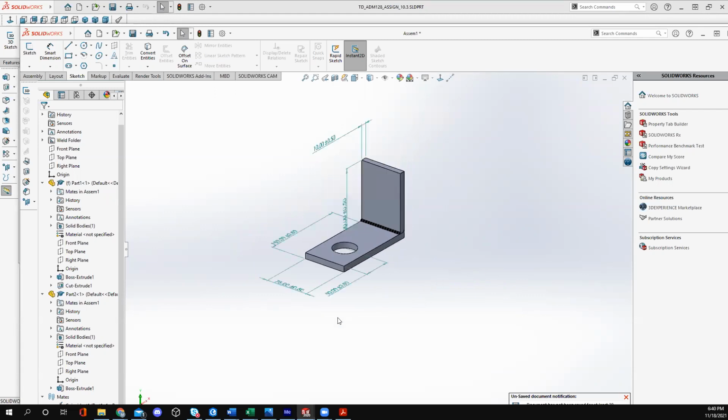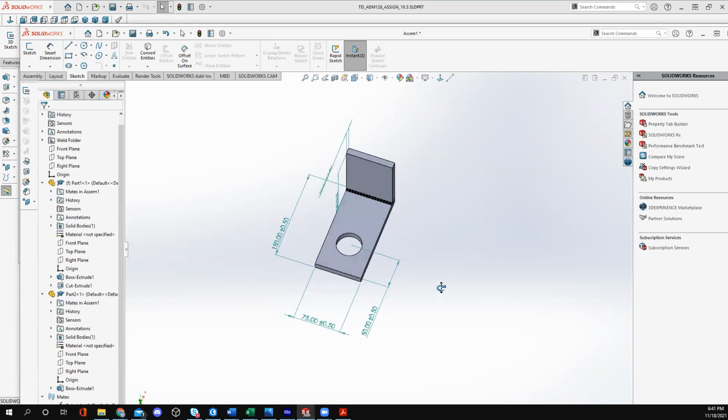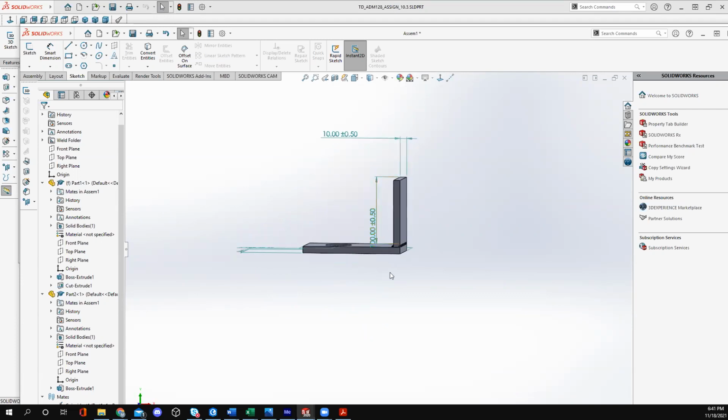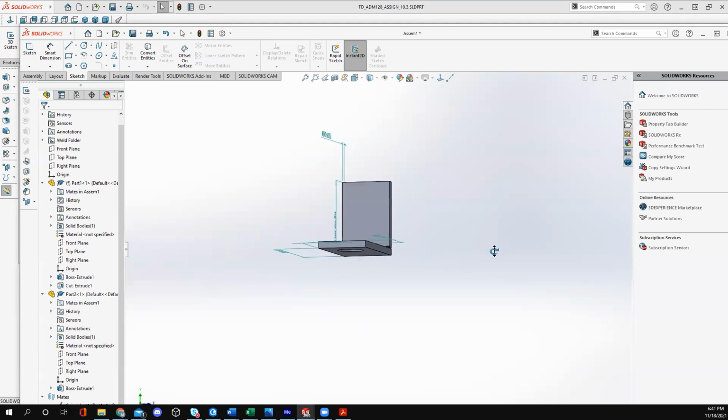You don't have to do an isometric view unless you like drawing things with vanishing point type geometric drawings, then go for it. This would be a pretty simple one to do. All these lines run to the same vanishing point somewhere over there, and all of these vertical lines run to a vanishing point. I think down is the vanishing point, but it's so short that you can't really tell. Like I said, you don't have to do this drawing, but I do want a top down, front, and side, or top down, back, and side.